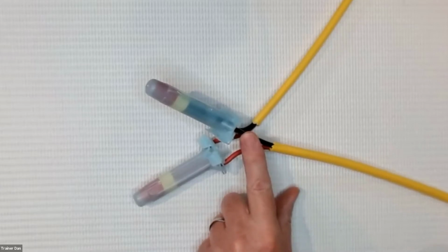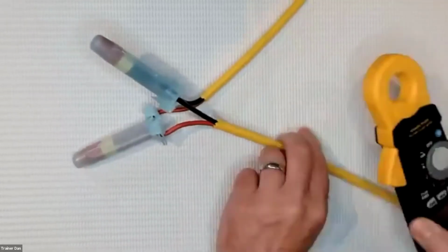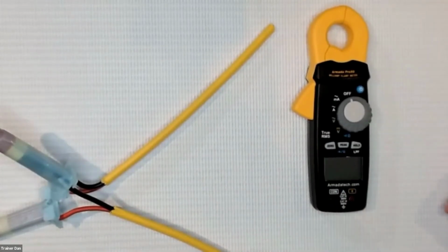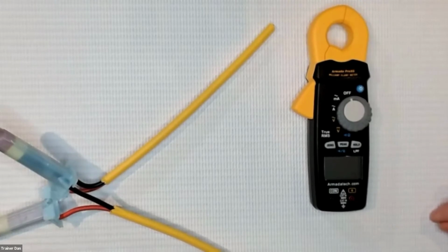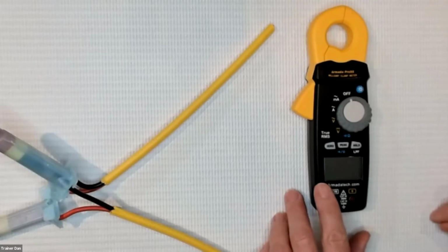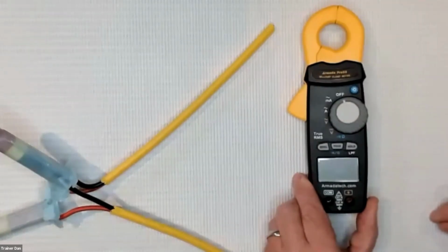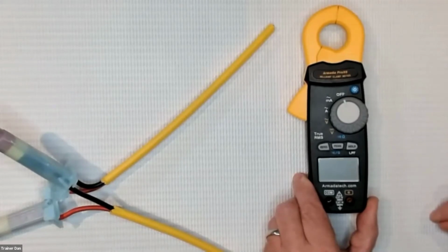So the tool for troubleshooting a two-wire path is going to be a milliamp clamp. So this is a milliamp clamp. A milliamp clamp is a clamp amp meter that can read down to 1/1000th of an amp, so 0.001 amp can be read by this. Now, you may have an amp clamp that you use for checking motors or other things like that. Chances are it doesn't read down that far. So a milliamp clamp can read down to a very small unit.